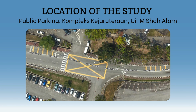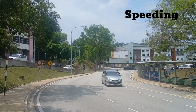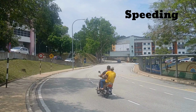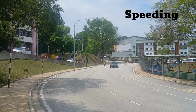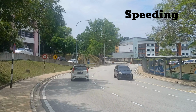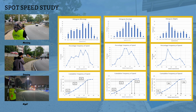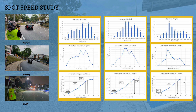The location chosen for the road safety audit is an unsignalized T junction at the public parking complex, Kejuruteraan UiTM Shah Alam. The first issue of the T junction is cars on the major road speeding downhill above the speed limit. Through observations, there was no signage visible for the downhill vehicle direction, and there was also no traffic control device such as a speed hump or speed bump. This further contributed significantly to the speeding behavior.